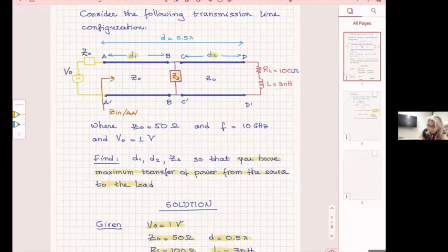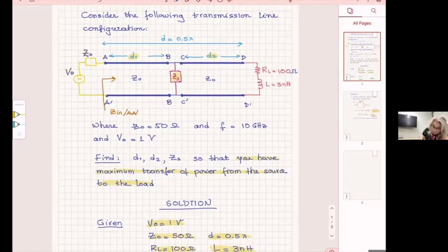So instead of spending another additional length to find Z naught, what if I make this one here to be Z naught? If I can do that, that makes the reflection coefficient there 0, and at any other point of the line, the input impedance is going to be Z naught. Am I right when I make that statement?